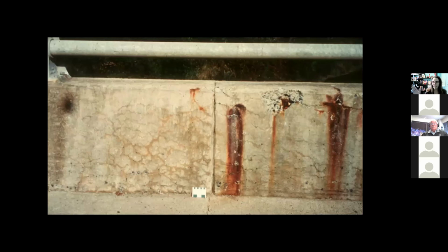But just looking at it, I would want you to tell me that you see staining. You might want to guess it's rust. You see a white deposit that may or may not be efflorescence, may or may not be ASR gel. You see map cracking, and then you take lots of photos that tell the story better than your words do.